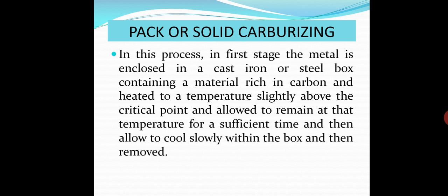So, we have chosen a solid material which is rich in carbon, and the metal is enclosed in a steel box containing this material, heated to a temperature slightly above the critical point, allowed to remain at that temperature for a sufficient time, and then allowed to cool slowly within the box and then removed.